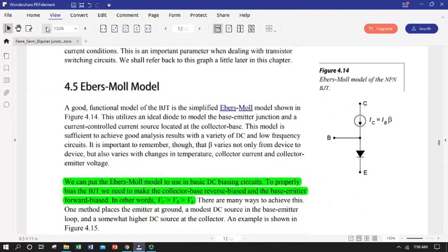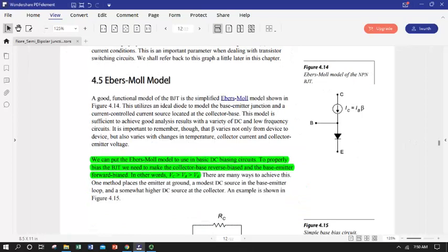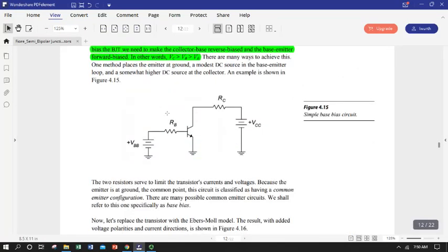Okay, last topic of this lecture is the Ebers-Moll DC model. And that's to account for how we actually use transistors in circuits. How do we design a circuit around it and analyze it? Because we've got a lot of nice stuff. We've got some precautions, but we've got this fabulous device that can give us a constant current under certain circumstances, that has this particular relationship between base current and collector current, and has this crazy steep slope, then a plateau in the current-voltage relationship. And it's a little tough to account for all of that in what's going to be a voltage drop somewhere in a circuit, or how much current I'm going to have flowing through one part of the circuit where I have a transistor.